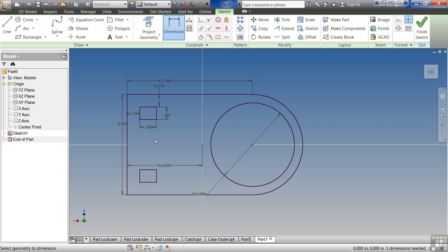Create the shape you want by using the dimensional constraints, perpendicular, parallel, tangent, symmetrical, and then add your dimensions and define the size of it. Very easy to capture design intent, and it's a very powerful tool. So try to make your parts as smart as you possibly can.